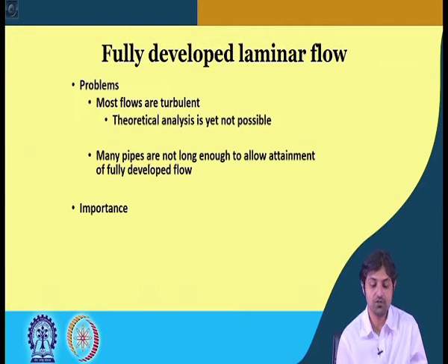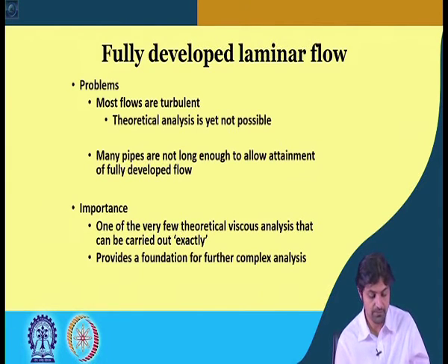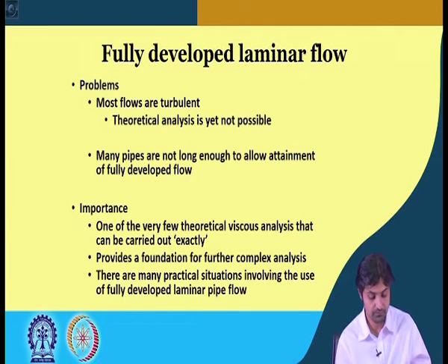Now, what is the importance of the fully developed laminar flow? There are certain problems related to it, but there are certain importances and advantages to it as well. It is one of the very few theoretical viscous analyses that can be carried out exactly, and we will see how in our upcoming slides and lectures. Therefore, it also provides a foundation for further complex analysis. There are many practical situations which involve the use of fully developed laminar pipe flow. We will see those examples later.